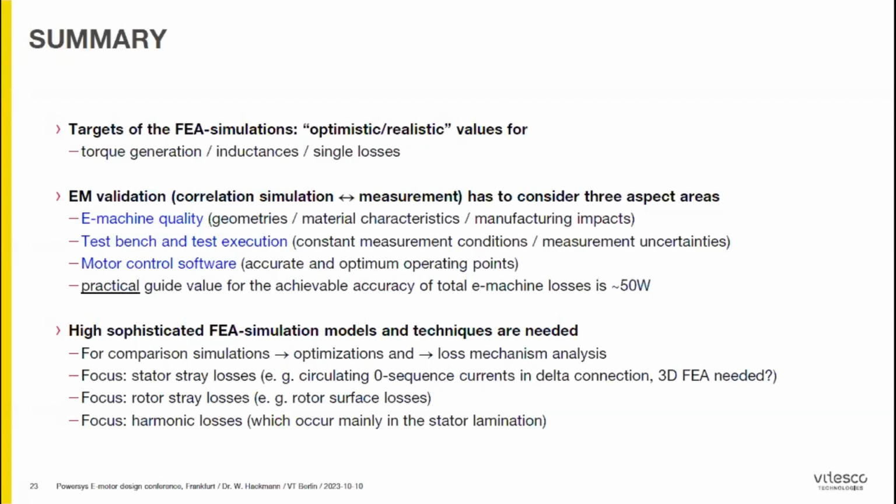And then it's clear, you have to separate this in simulation. And as we did this for endless winding, you can do this also with a normal machine, saying, okay, I define a region teeth and I define a region yoke, and yoke has other loss curves, and the teeth has other polarization curves. So this is a direction, and the rest is a feeling.